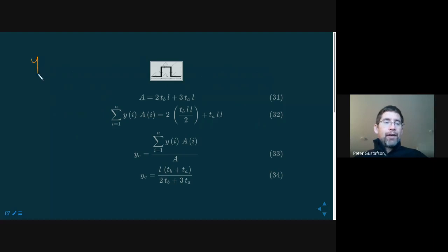In order to do that, remember, by definition, y of the centroid is the integral of y dA over the integral of dA, which can simplify. You can do this as discrete sums rather than integrals. Sums are sums, integrals are sums. And so I'm going to calculate the total area of the cross section. That's pretty straightforward.